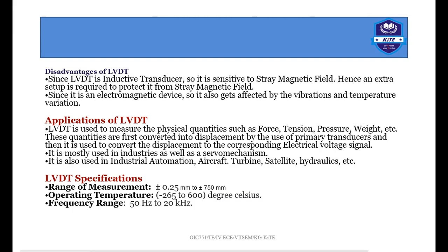So the LVDT specifications: the first point we have already observed. The range of measurement is plus or minus 0.25 mm to plus or minus 750 mm. The operating temperature is minus 265 degrees to 600 degrees Celsius. The frequency range is from 50 hertz to 20 kilohertz.